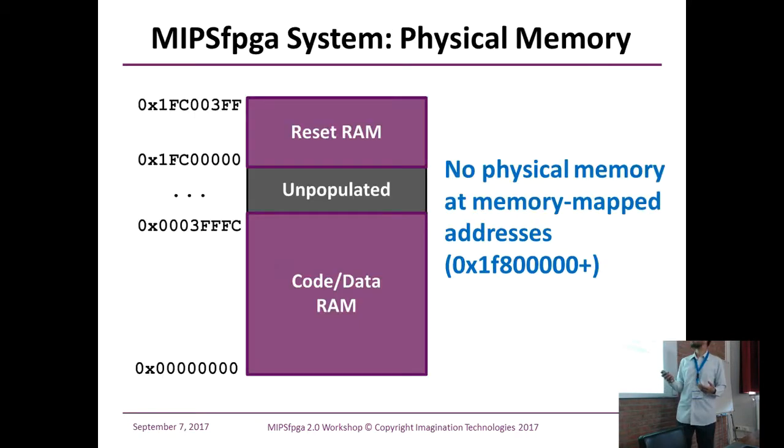One thing to note, the addresses are in the unpopulated memory map. We have a 32-bit address map, 0x000, 256 kilobytes of scratch RAM. It's up to this address. We have 1 kilobyte here, located here, 1FC00.